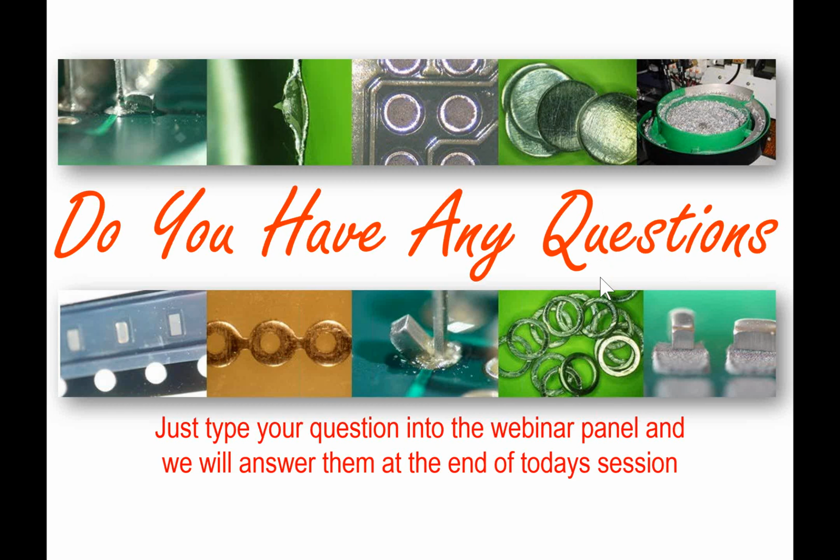If you look at examples of component warpage, we know the component warps, but engineers have to mess around with the stencils and put bigger blobs of solder paste in certain areas to overcome the warpage. That's an example where we've got to deal with the situation. It's not ideal, but that's what engineering's all about, I'm afraid. Trying to solve the insurmountable problem.